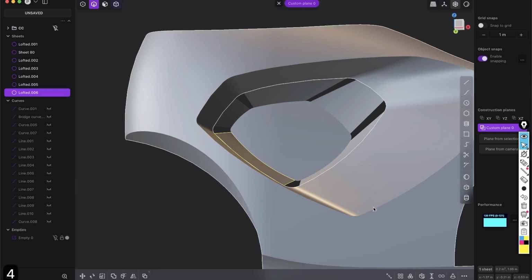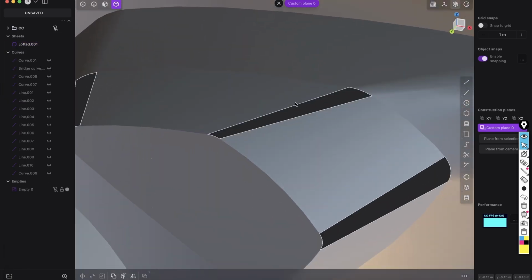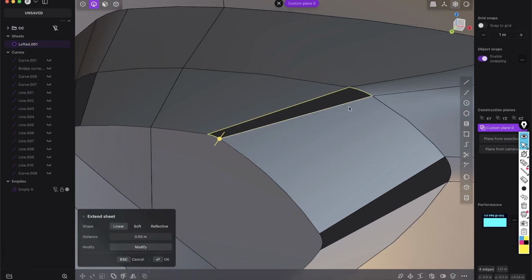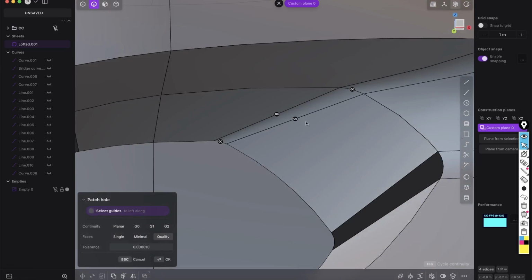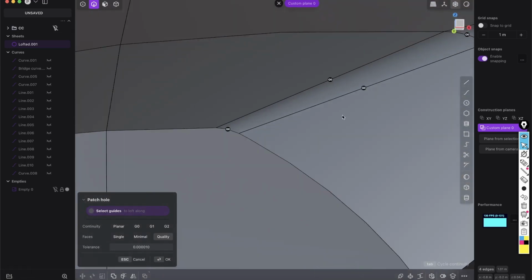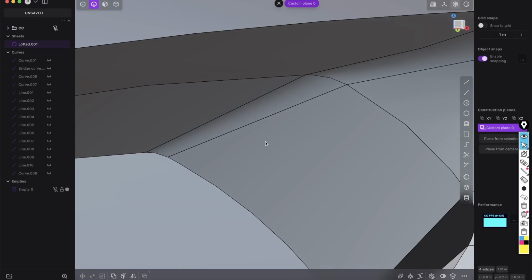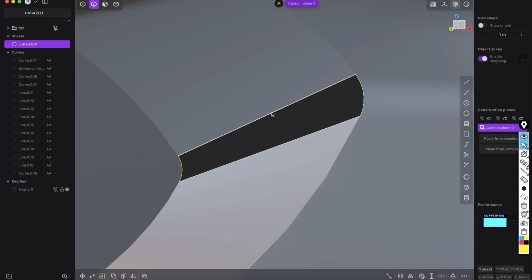And again, press 4, join everything. And because when it's joined, we could loft it, or you can just press edge mode and Alt click and select all of them and patch. So I have it on Shift 3, again, super fast with the left hand, everything you find in the PDF collection. And then we can just do it this way, and you see it works beautifully, and it's even faster if we would loft it.